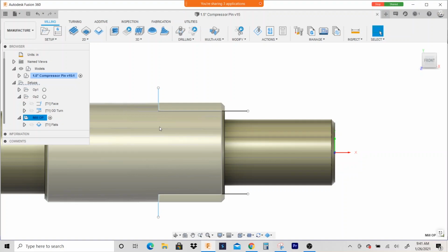And anytime you drop a tool in front of a part, and when you go to lead in and cut, you want to give yourself some kind of clearance. You don't want to drop the tool on top of the part because your tools can wear out faster. It's just not proper. You want to drop it in, then feed in.